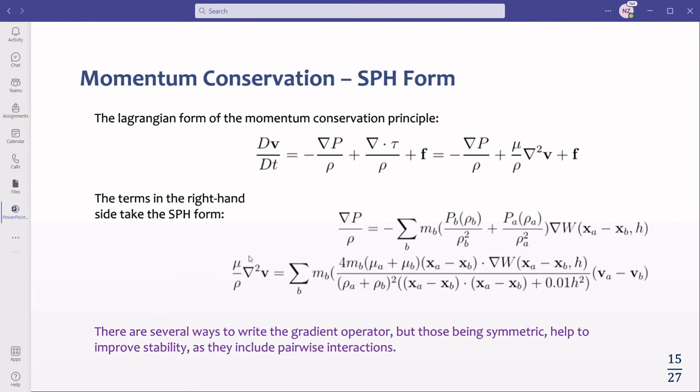And this is the expression for the Laplacian. Beyond looking at the demonstrations of this expression, the important part is all these values, see what is inside. If we want the Laplacian, we need the viscosities that may be constant, maybe not, depending on the particular application. But those are dependent on pressure and temperature. So we have the density here, but it also depends on pressure or temperature. The distances are known, at least in an explicit scheme, and the velocities.